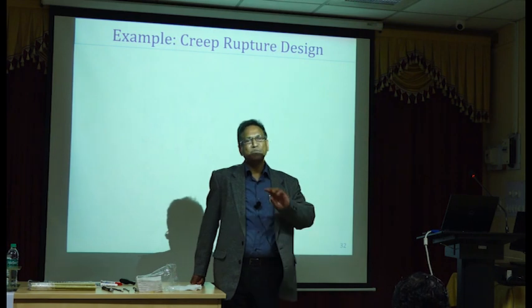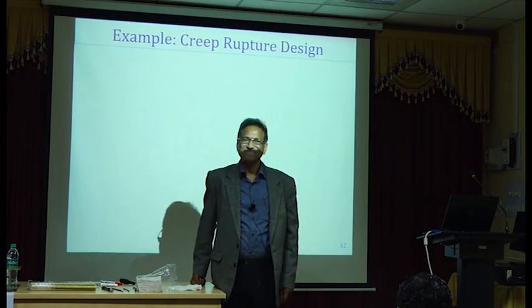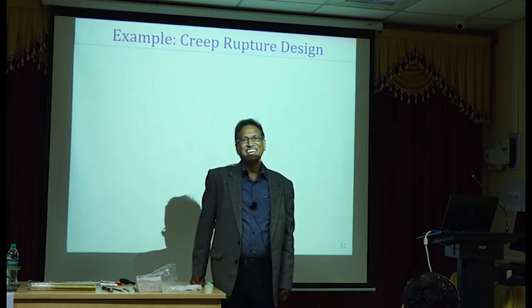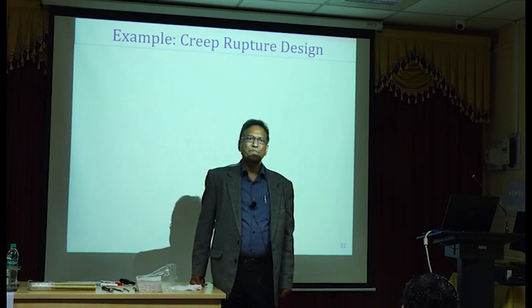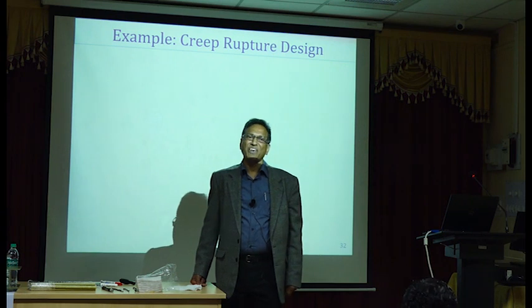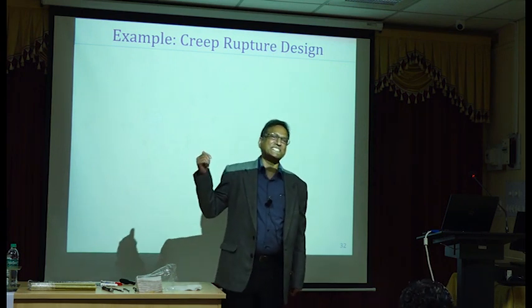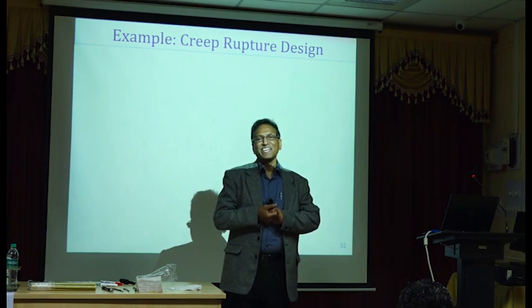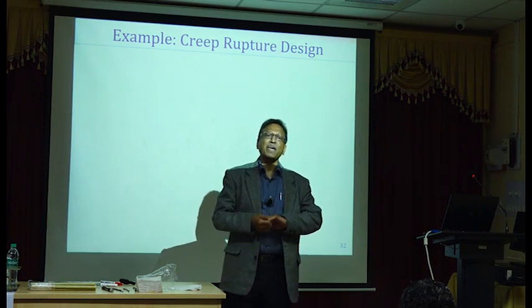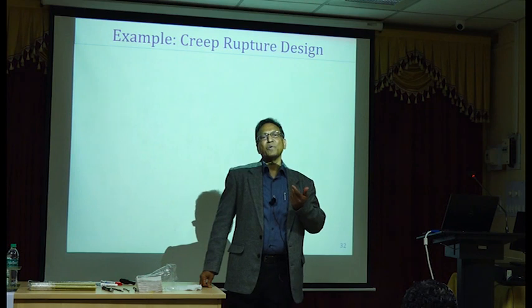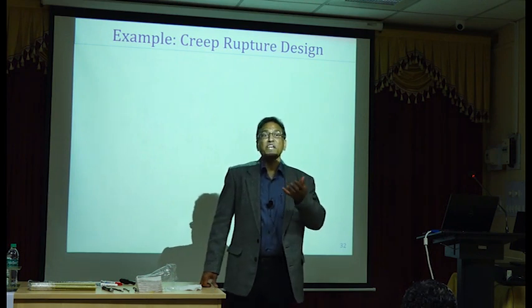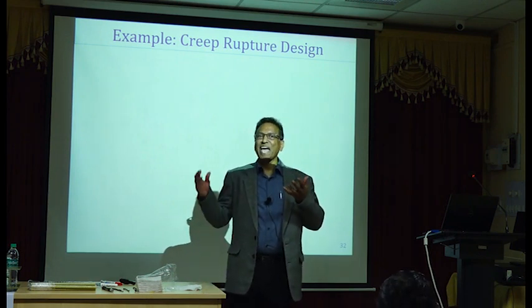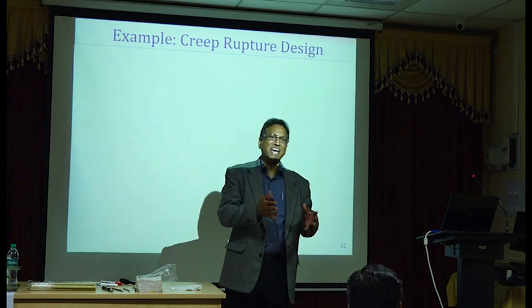Why? Because the FIB Model Code suggests two equations, for linear variation as well as parabolic variation. But ACI keeps it very simple. It is suggesting only one factor. So I want to include that the bond stress variation is parabolic. You can, but then you are dealing with ACI. Right? So it's conservative, but at the same time, you don't know many things. What you don't know, you are always afraid to use. And if something happens to the structure, once you design it and build it,